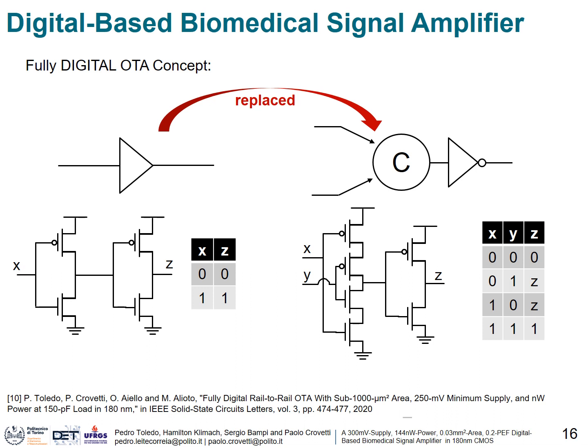Before understanding how the common mode input signal is fixed, a little change must be made in the buffer topology to make it possible. Now, instead of using two cascaded inverters to build a static buffer, we have to change the first inverter to a Muller-C gate, adding a new input in the signal path. You can see from this table on the right that the Muller-C based buffer only changes its output when the logic levels are equal, otherwise high impedance mode is triggered.